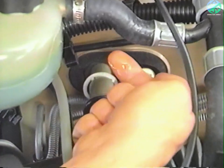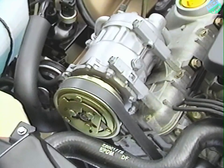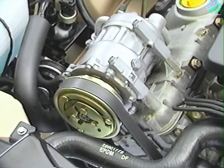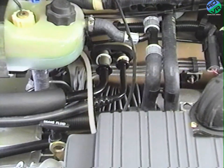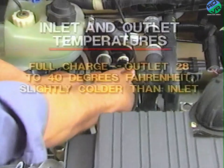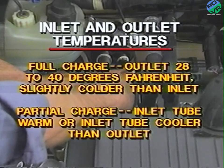Now, oil near fittings or connections indicates the system has been leaking. One sign that low refrigerant is the cause of insufficient cooling is a compressor clutch that cycles rapidly. Feeling the evaporator inlet and outlet during AC operation will help confirm low charge in the system. On a system that has close to a full charge, the outlet will be 28 to 40 degrees Fahrenheit and will feel slightly colder than the inlet. On a partially discharged system, the inlet will either be warm or it will be colder than the outlet tube.